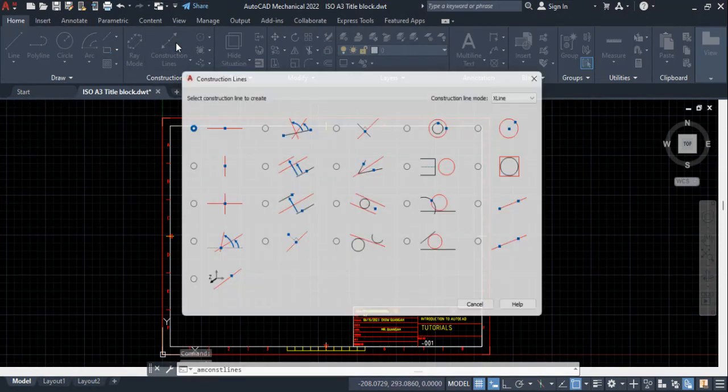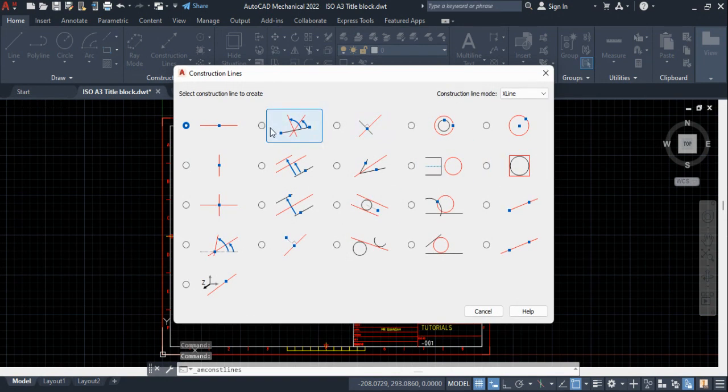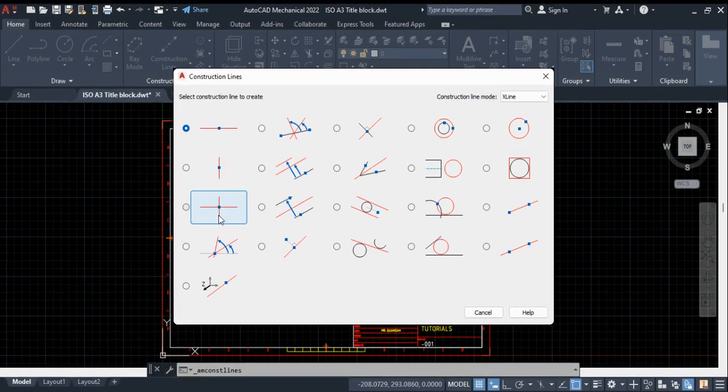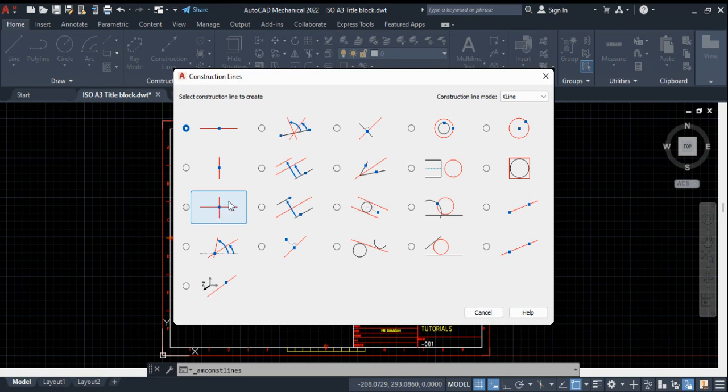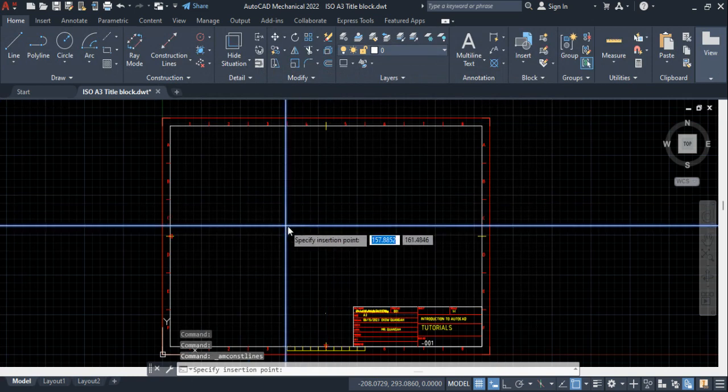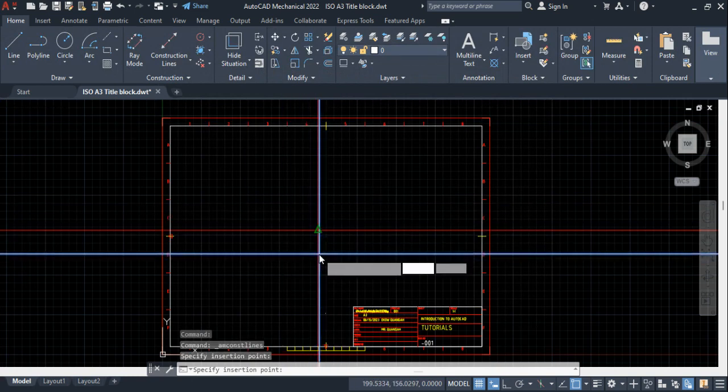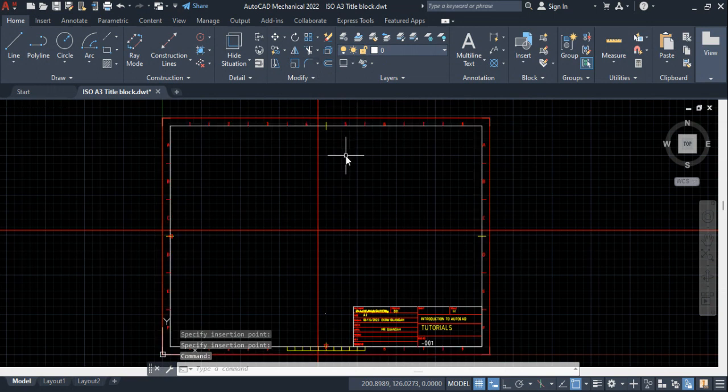So click on the construction section. We have different types of construction lines you can create. You have horizontal, we have vertical, we have construction cross and all of that. So this particular command will come very handy when you are learning projections. All right, so we have different types. So for example, when we are drawing our axis for our projection, so this is what you use. You can specify your, and then you press enter. Then you've gotten your construction. Then you can start your drawing.